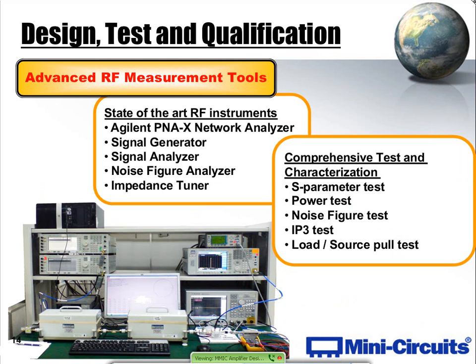After the part is designed and after all of that work is brought to a tape out and you get your first parts, there is a significant amount of effort in qualification and characterization. And characterization is a multi-week event. It takes a large team to prepare a whole battery of tests to fully characterize the part, to see A, do we achieve our design goals, and B, to understand the limits of the part, so that when you create your data sheets and your design and your documentation for your customers, you can put the part into the market with a high degree of confidence.